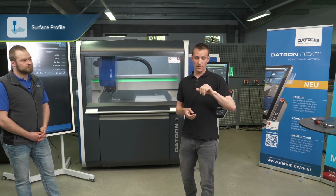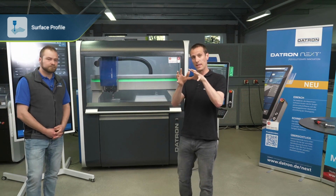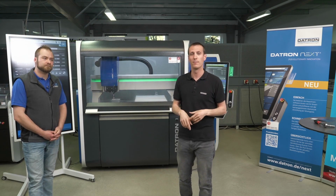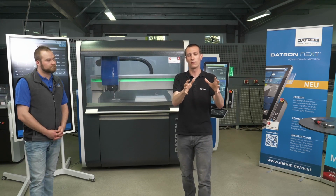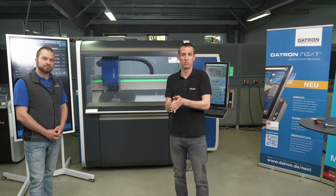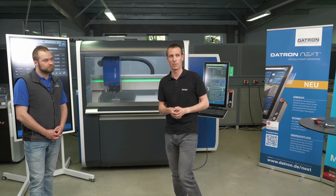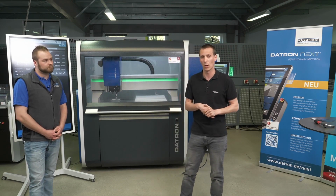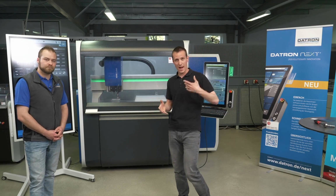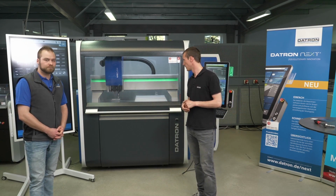New in the actual software, which just came out, is that if you want to build in the measuring cycle that you have done with your finger, you can just copy this information and bring it into the code. So if you set the job up and want to start it on another day, you don't have to do this setup again. You can directly copy the code to the actual cutting program, and it will be executed as well.